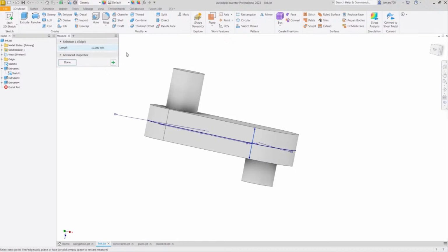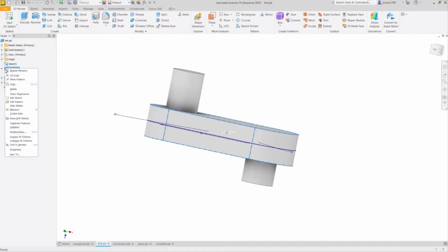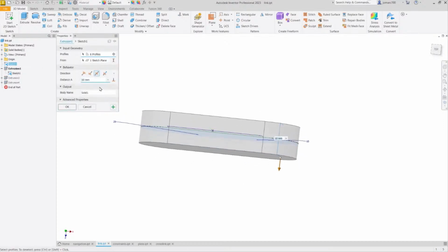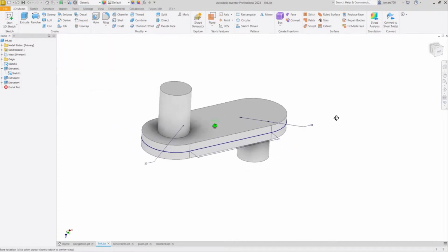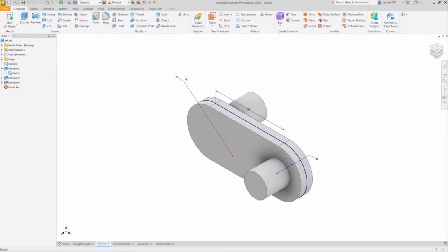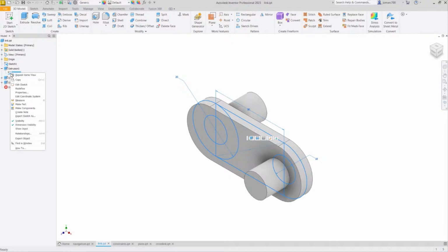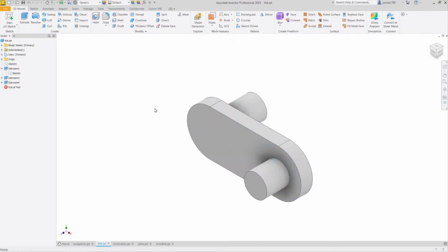So with that, let's do another revision, hitting escape, heading to extrusion 1, right click, selecting edit feature, and instead of 10, revising this to 5. Selecting OK, hitting F6, and let's turn off the visibility of sketch 1. Selecting that on our browser tree, right click and disabling visibility.